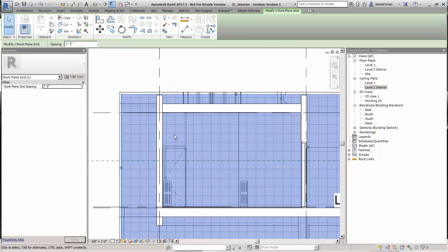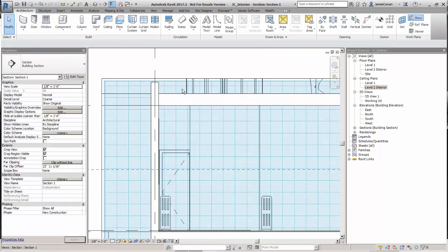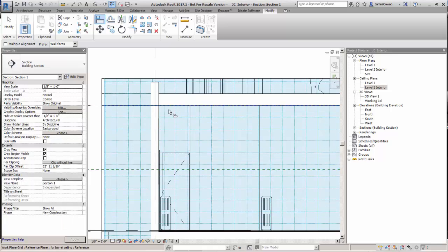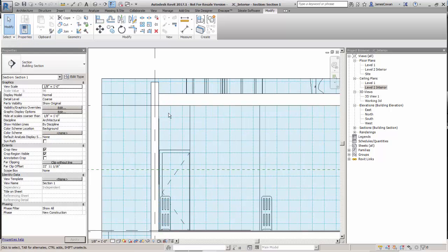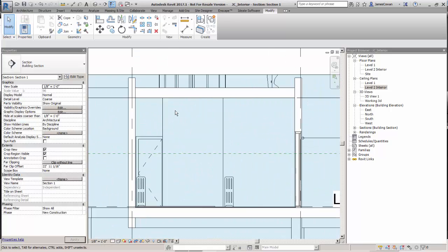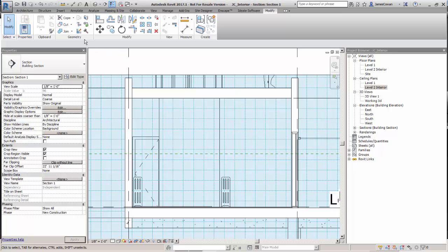And I could even do things like say, align. Let's modify. A line to the underside of the ceiling, that line on the grid, and to the face of the wall, that line on the 1 foot grid. So I could use those to snap to points if I wanted to do that in my project, or I could just draft it and be precise about what I'm drafting.